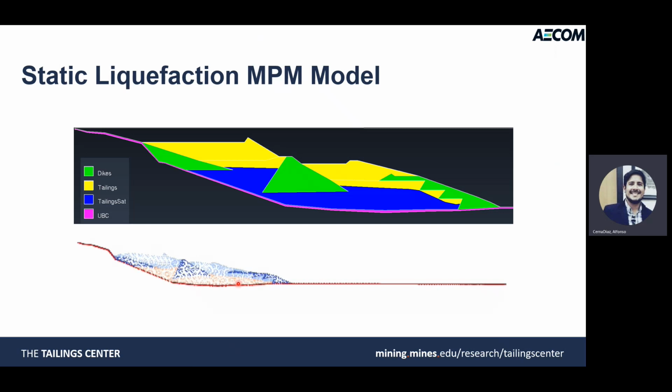There are other analyses in which you already know the case history trigger. However, you're more interested in your runout analysis, how much your flow mass will travel. So this type of MPM analysis, or material point method, will help guide the type of evaluations that you need.